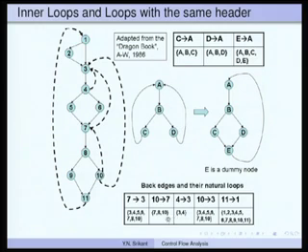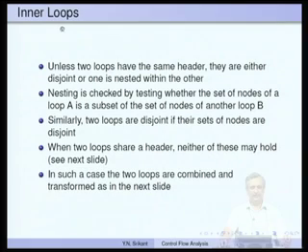But the same is not true between these two. There are no nodes which are shared. So, these two are disjoint loops. But 10 to 3 is again 3, 4, 5, 6, 7, 8, 10. So, 7 to 3 and 10 to 3 are identical, so there is no question of nesting here, they are identical loops. 11 to 3 nests all other loops, because all others are strict subsets of this particular loop set. That is what we mean by nesting of two loops.